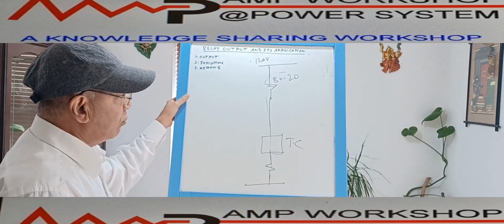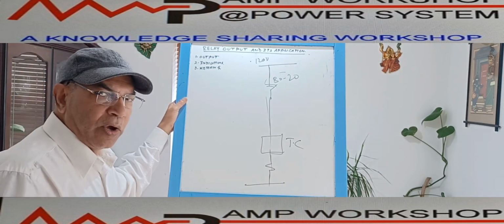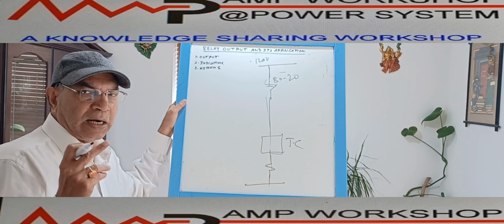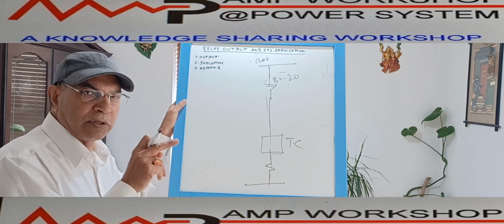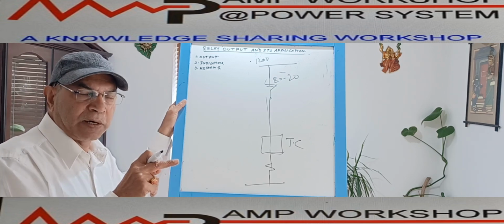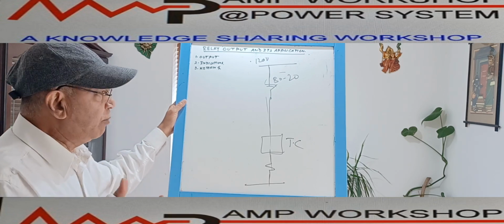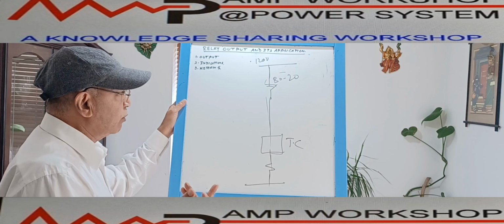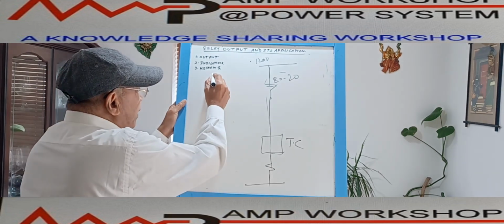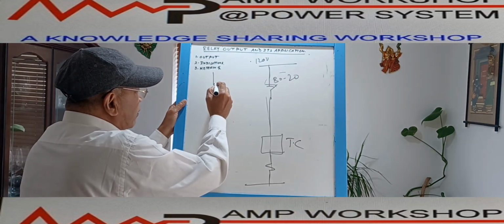Similarly, as we have done the closing circuit, now in the same way we can trip the breaker, so that I can do two ways. Suppose there is a button on the breaker. If we press that trip button, then the breaker will trip. In the same way as we discussed in the closing circuit, I can make the logic for this button.